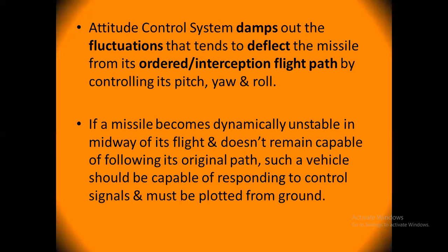There are three things we'll be discussing now for attitude. Basically, for stability there are three different types that come into picture. First we'll understand these, then we'll see what dynamic instability is. First is the positive stability. For example, you release the missile and there's a disturbance which you have given to it. Now the missile will go into unstable mode, because you have given a disturbance, and slowly it will try to come into the stable mode. So after going into instability, it will come into stable mode. This is called positive stability.